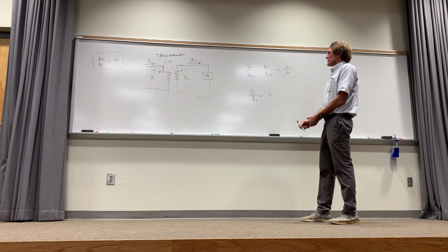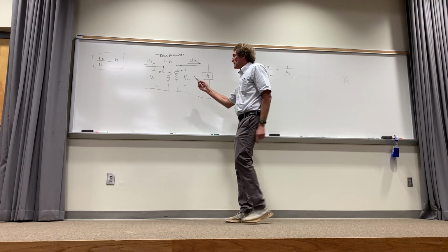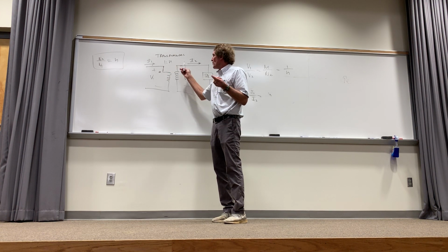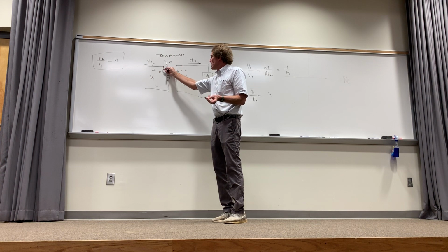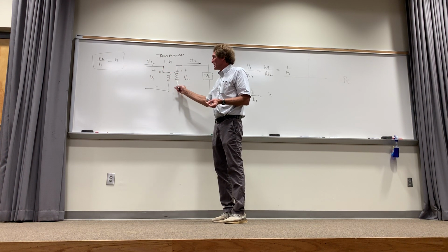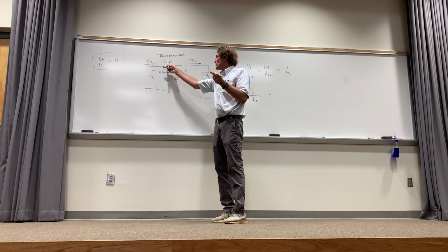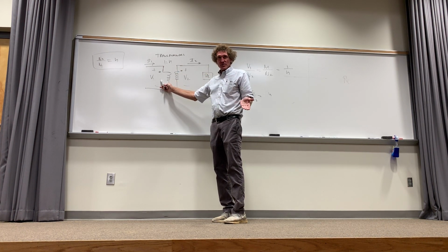And really what I'm saying, I do it this way. I don't even really pay attention to that. I always say, when I look at this, if I go from 1 to 2, I know voltage is greater here by a factor of 2 than it is here. If it's 1 to 5, voltage is greater here than it is here by a factor of 5. That's how I look at transformers. Now if it was 2 to 1, I know this voltage would be 1/2 this voltage. This is how I always do it. Do y'all understand this, class? I'm trying to show you the way.